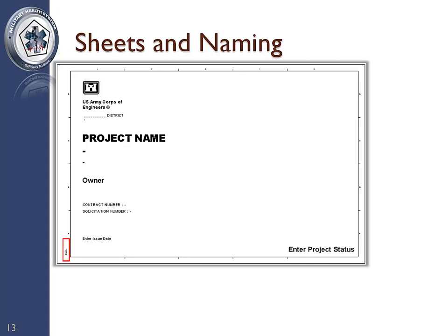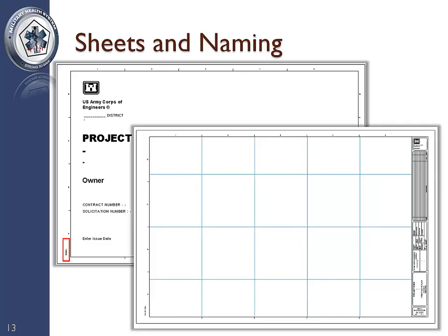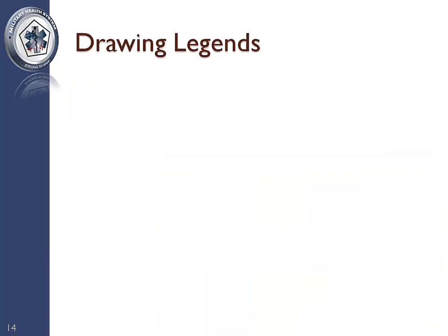Project and sheet parameters can be set up by the project user that will include the AEC sheet name on the left-hand side of the printed drawing sheet. These will be placed outside of the sheet border. Standard ANSI D USACE border sheets are included in the template as an annotation family.